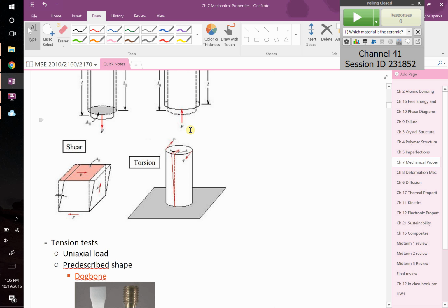You can do shear. Shear is when you apply a force that is no longer perpendicular to the face, it's parallel. So when I push on this table, when I'm leaning on it, part of my force is still pushing down, right, because I'm not glued to the table. So there's a component of regular compression, and there's a component of shear, where I'm actually shearing this table. The floor is holding it, so there's an equal and opposite force. I'm pushing it this way, the floor is holding it with an equal and opposite force that way, but the table technically is deforming a tiny bit. It's just not so much that we can see it, right?